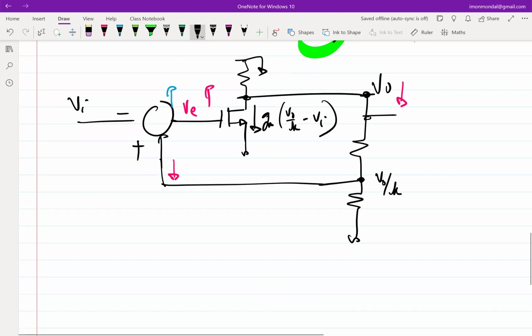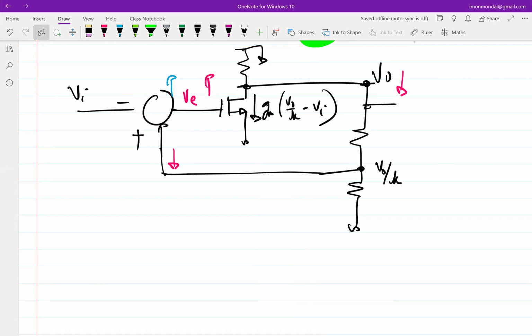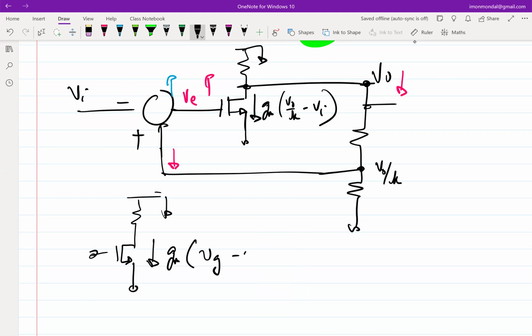So let's only focus on this part. In a transistor, this current is essentially Gm times Vg minus Vs, right? Trivial stuff. So the ultimate goal is to get rid of that ideal summer, right? So can I do something to ensure that this current that is coming out from the common source amplifier in the circuit on the top is the same as whatever it is supposed to be? If I look at this current equation in the bottom, what should I connect to what?